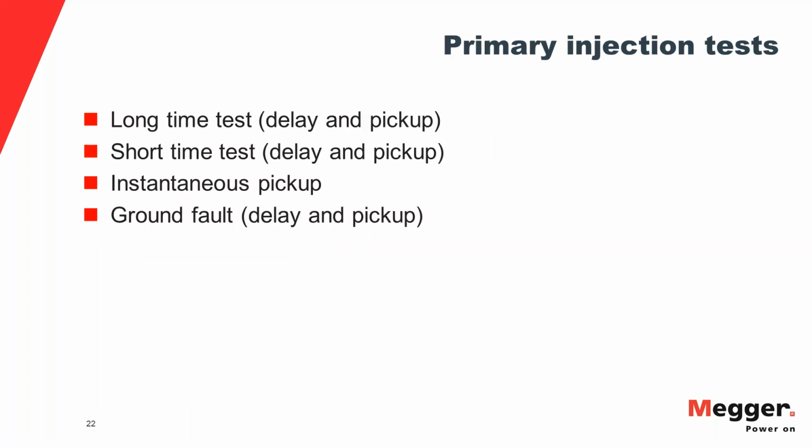There are 4 types of tests that are done as part of primary injection testing. There is long time test, there is short time test, there is instantaneous pickup, and there is ground fault. Let's talk about each of them. So you have the long time test.